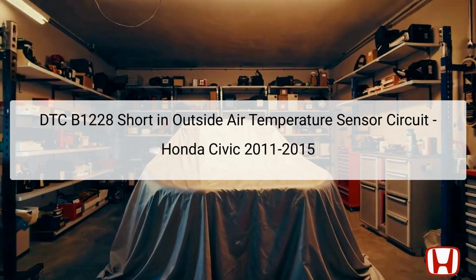The DTC B1228, commonly referred to as a fault in the outside air temperature sensor circuit, is a significant error code that can impact the performance of various systems in the Honda Civic models from 2011 to 2015. This diagnostic trouble code, DTC, indicates that there is a short circuit within the wiring of the outside air temperature sensor. The outside air temperature sensor plays a vital role in monitoring the ambient temperature and is typically located at the front of the vehicle, near the grille or the front bumper.